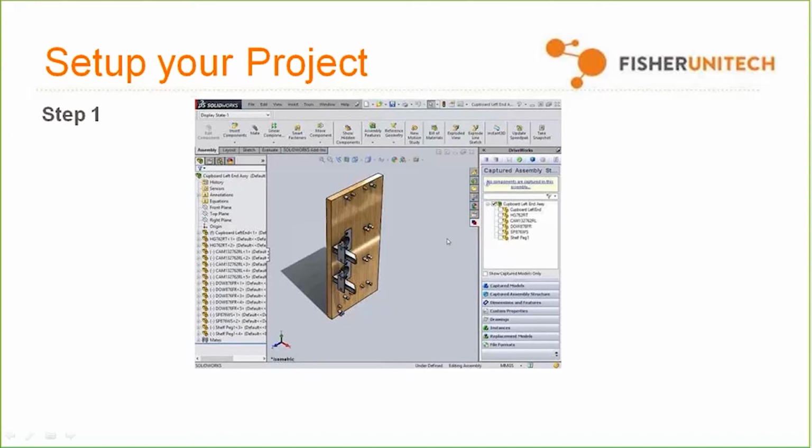Also on the Replacement Models tab. So again, let's say that I wanted to do a quick static replacement, and by that I basically mean nothing about the size of the bracket is going to change. You could swap out a different component, and that's essentially going to do the same as a replace component if you were to right-click on any given component and then choose that from the sub-menu.